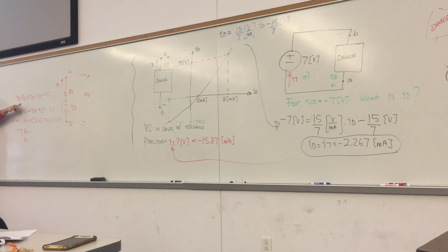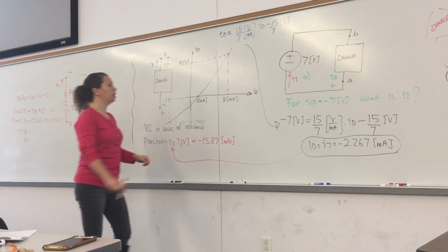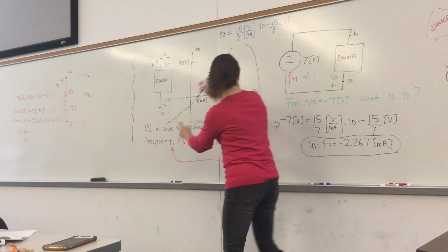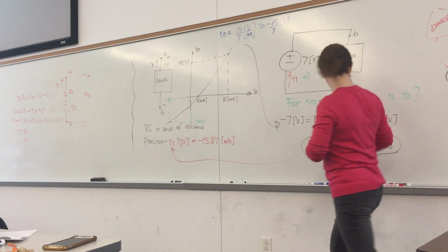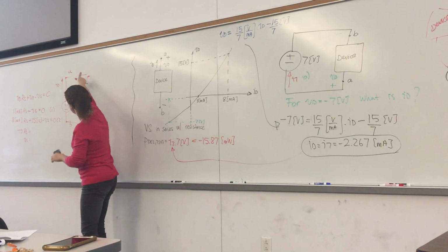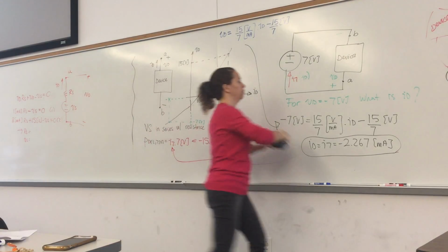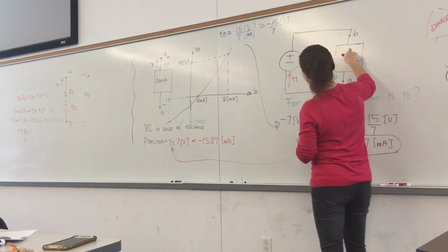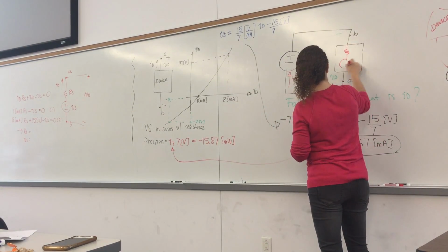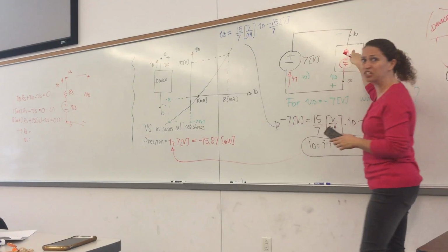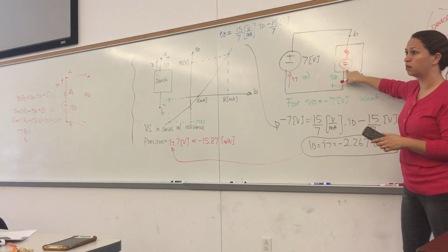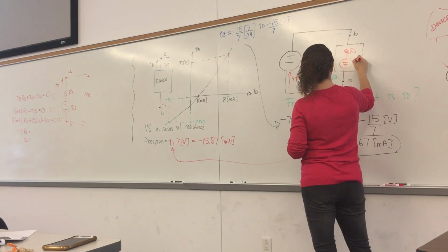Once you get the model, now go to the circuit that it's connected to, replace your device with the model, right? How do I do that correctly? Be careful, the device is flipped, right? So what I'm gonna be doing is, my original model, how I picked, the B side has the minus sign. Don't forget. So the B side should have the minus sign here, right? Resistor is in series, right? It doesn't matter if I put it here or here. So that's RS, that's VS.